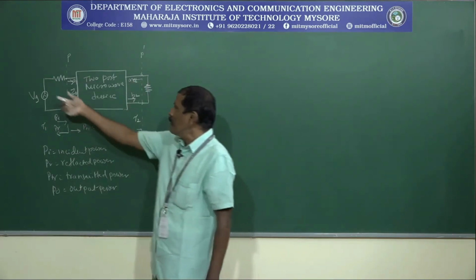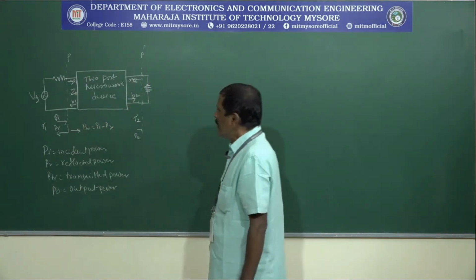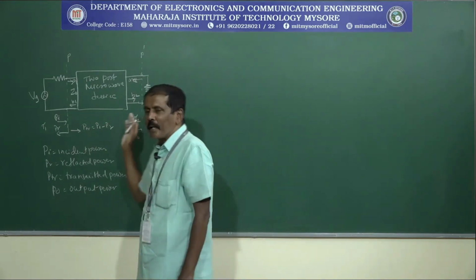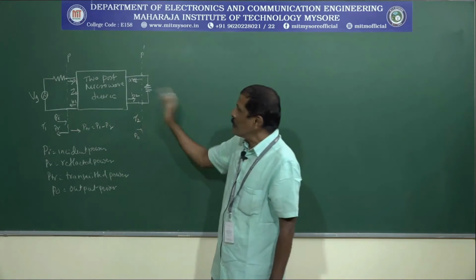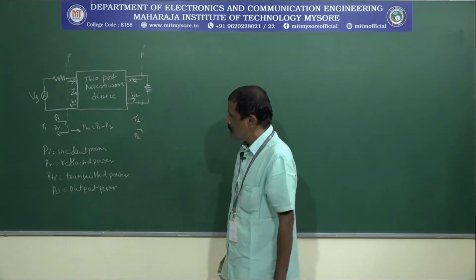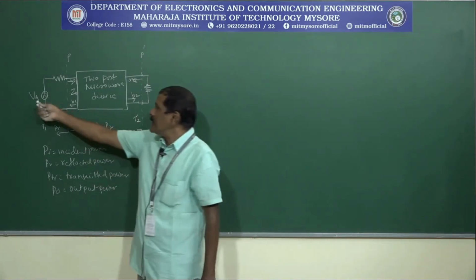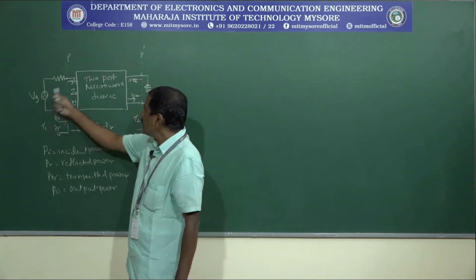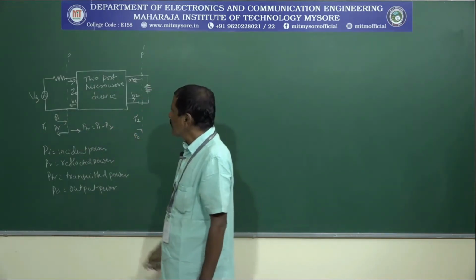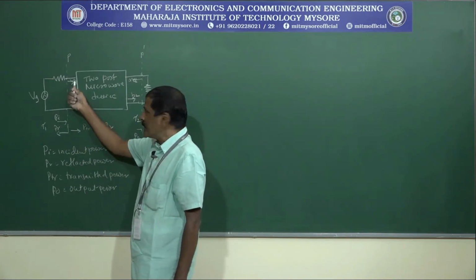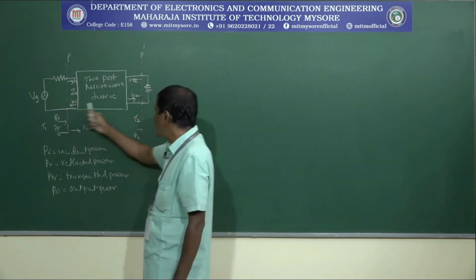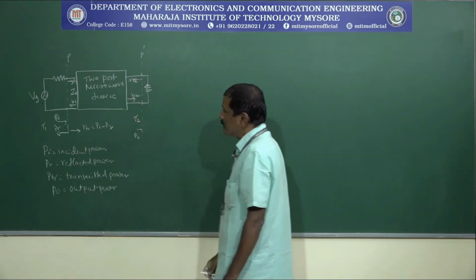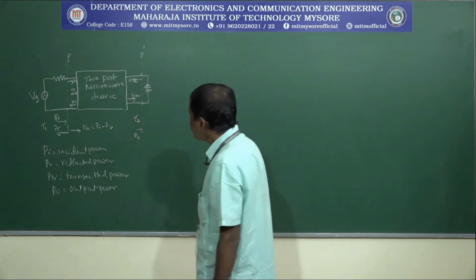As you already know, whenever a signal is incident on this particular network, depending upon whether the load is matched with the characteristic impedance, you get reflected waves, where Vg is the input voltage. Now this input voltage is applied to this network, where A1 is the incident signal and B1 is the reflected signal, and here A2 is the reflected signal and B2 is the incident signal.